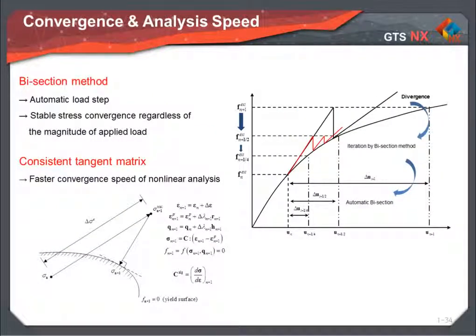Another significant improvement has been introduced to improve convergence of analysis. Nonlinear finite element solution is a method of converging the accumulated incremental solution from iterative calculations to the correct solution, and it is processed as shown in the figure on the right hand side. GTS NX provides the automatic tangential stiffness update, which judges an appropriate recalculation point by considering the overall characteristics of the nonlinear problem, such as convergence characteristics or determination of divergence.